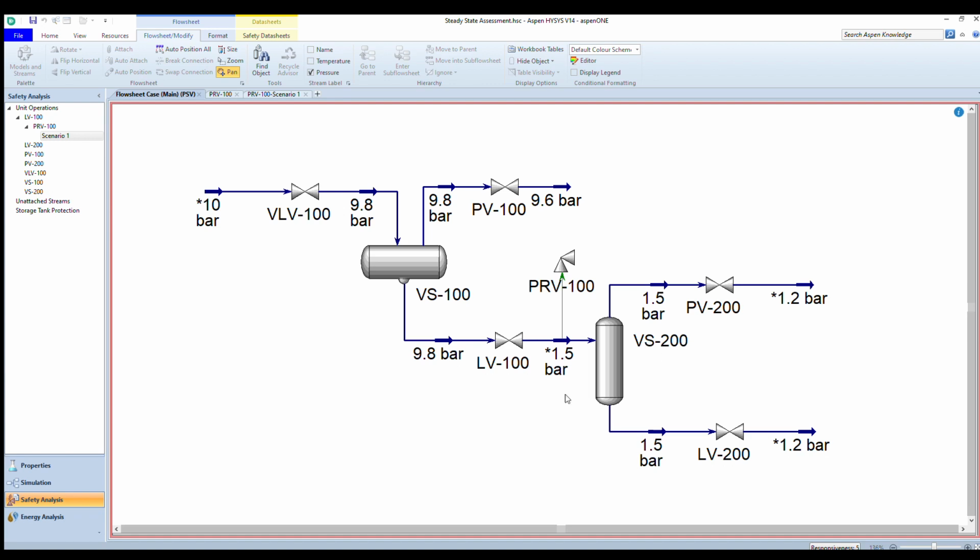pressure of 1.5 bar. Qualitatively speaking, and in compliance with API 521, this gas blow by through the control valve failure will necessitate an overpressure protection. So this is qualitatively speaking. There is no dynamic assessment upfront to be done to establish the need to have a PRD. So this is just an over-conservative approach in API. Whenever you have an HPLP interface, a PRV is needed.